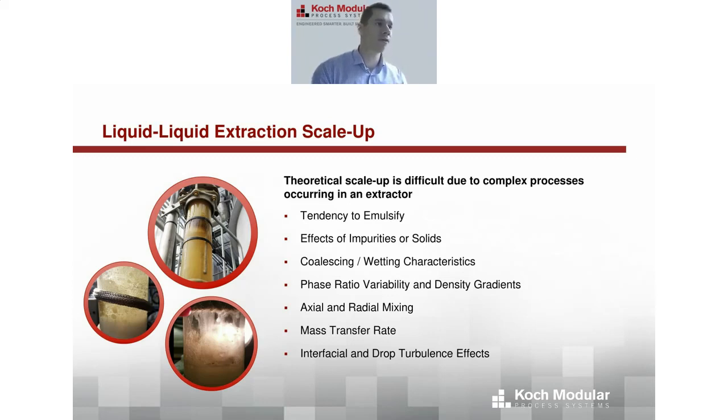A few of these things are highlighted on this slide. What I like to focus on is whether a system has a tendency to emulsify, what effect impurities or solids can have on the extraction process, and, kind of like Don was discussing earlier with the packed column, what the coalescing and wetting characteristics are like when you actually have the liquids flowing through an extraction column.